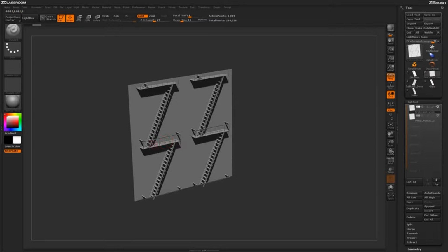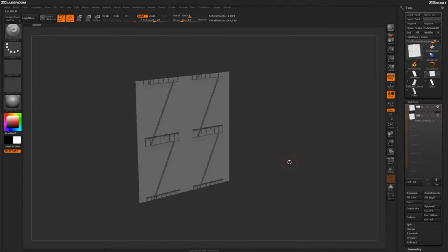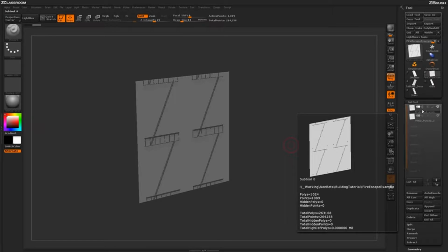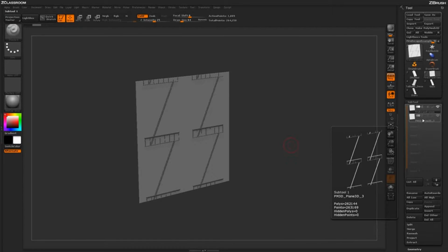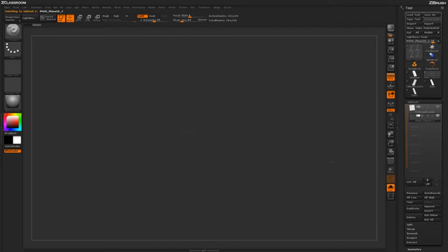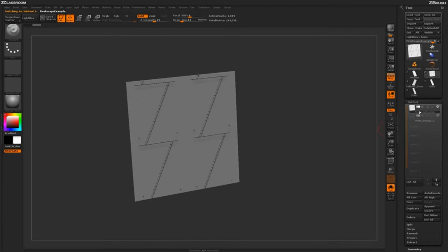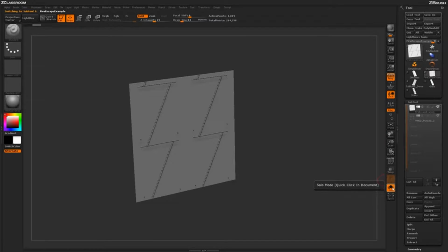So you can see I have the railings and the staircases, and it's generated in this tiling fashion. Now if I rotate this model right now, you'll notice that this 3D effect is going to vanish, and I'm just left with something like this. So if I come over here to my subtool panel, you'll see that I just have two subtools. And if I turn on solo on both of these, you'll see that these are literally single plane geometry. So this is just two plain 3D objects that I've then applied surface noise to generate this effect.